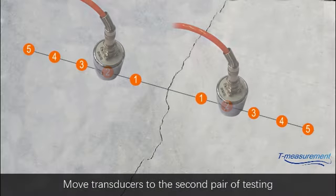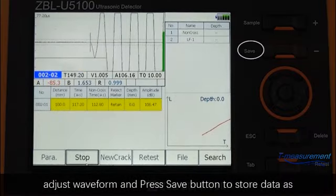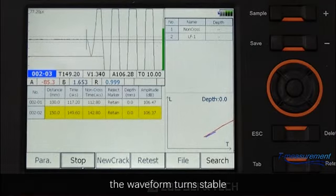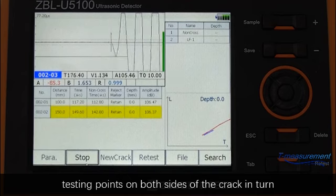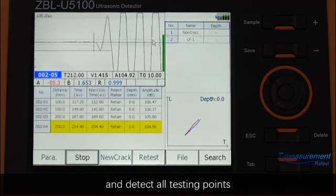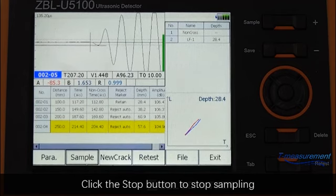Move transducers to the second pair of testing points at the same time. Adjust the waveform and press Save button to store data as the waveform turns stable. Move the planar transducers to other symmetrical testing points on both sides of the crack in turn and detect all testing points. Click the Stop button to stop sampling.